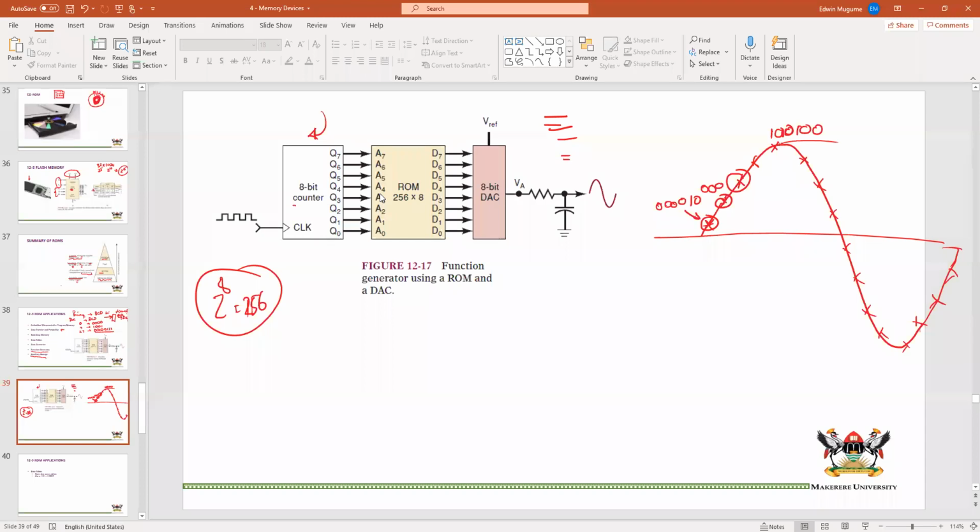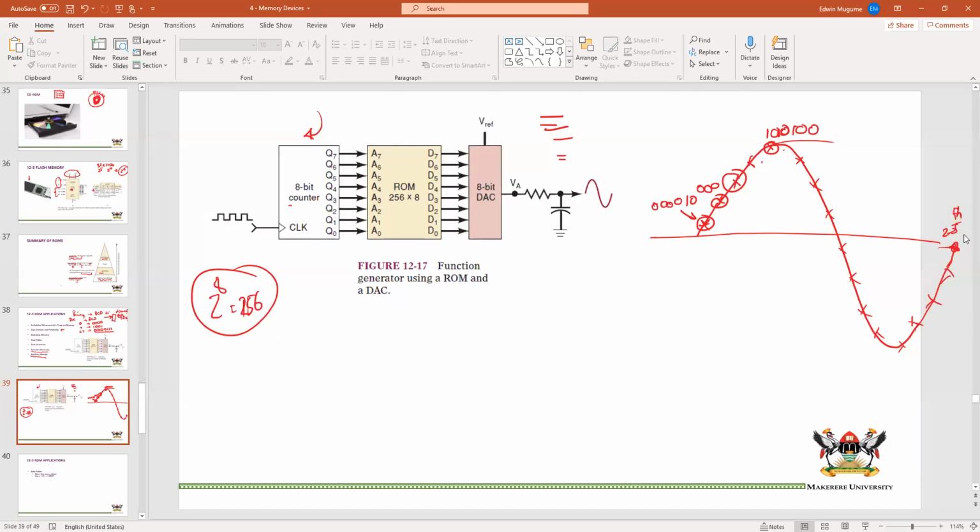So that you will store that register, and then register 1, 2, 3, 4, 5, 6, all the way to that one. And this is your maybe 55th register. So when you clock, you start reading from the first register to the second, to the third, to the fourth, all the way to the last. And then your clock will take you back to the first one.